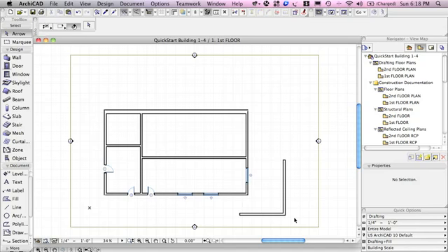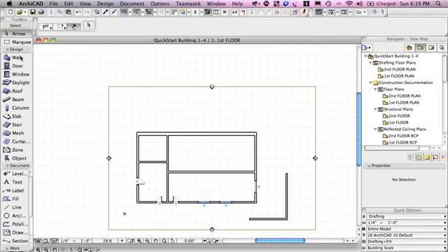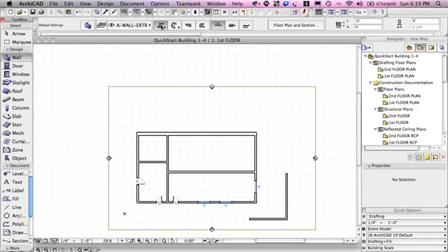So at this point, we've looked at some of the main options we have when we draw walls for the geometry of the wall, in terms of doing single walls, multiple walls, in a variety of ways. We haven't looked at the curved options, but those we'll get to later. We have looked at the construction methods, left, center, and right, to see how that affects the placement of the walls.